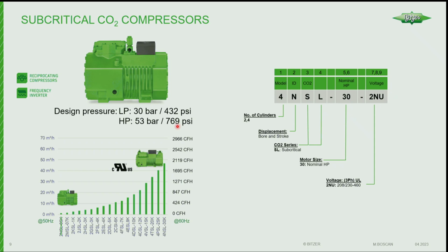Some people look at 769, and usually this is at the OEM level when they're doing the quality inspection before they put it in. They'll want to check it for leaks. We do this at our factory, and if they pressurize it to 770 pounds, they say it leaks. And yes, 99% of the compressor is low side. Only half of the cylinder heads are on the high side. So it will leak if you do that. So just kind of keep that in mind.